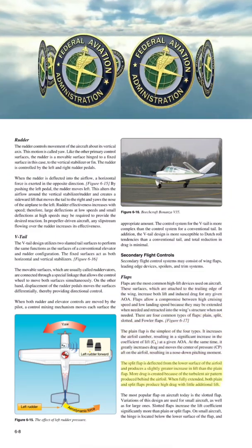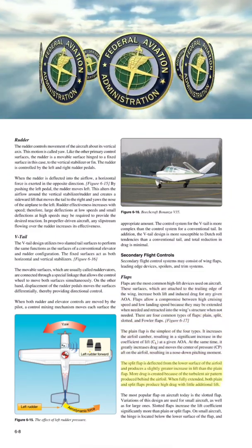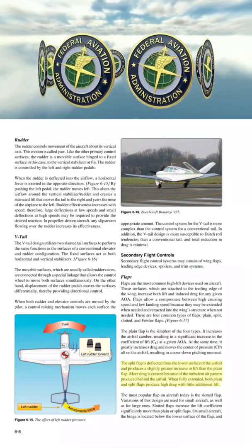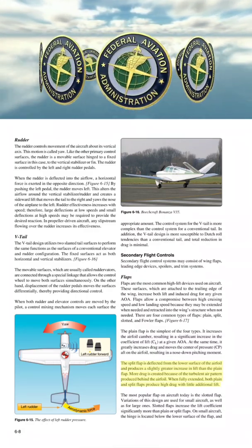The split flap is deflected from the lower surface of the airfoil and produces a slightly greater increase in lift than the plain flap. More drag is created because of the turbulent air pattern produced behind the airfoil.